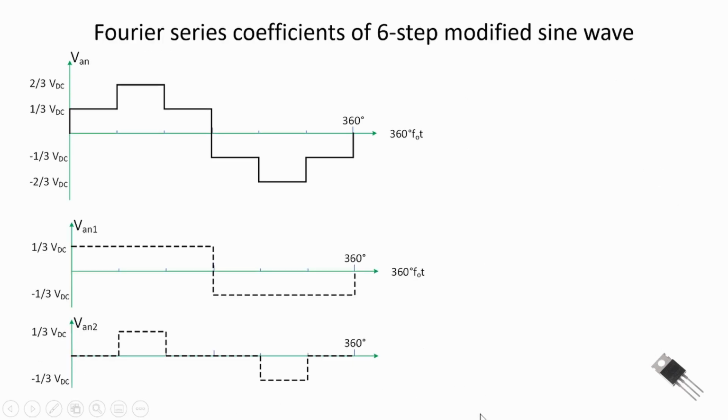So before we compute the total harmonic distortion, one of the things we'd like to find out is what is the power in the fundamental harmonic, our B sub 1. For this waveform, it has odd symmetry, so our A sub 1 is going to equal 0. So we'd like to find our Fourier series coefficient for B1. And one of the ways we can do that is through superposition. So we're going to use superposition on this problem.